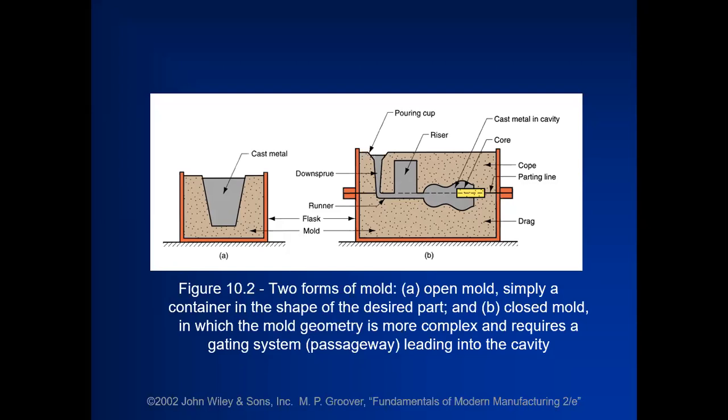There are two types of riser. One is called closed riser and one is called open riser. The riser shown in the figure is a closed riser. In that case, the riser doesn't give us information about the filling of the metal in the whole cavities. However, what you are talking about is the open riser.